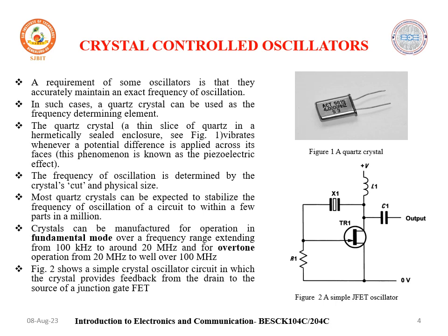A crystal oscillator generates electrical oscillations of constant frequency based on the piezoelectric property of the crystal. A requirement of some oscillators is that they accurately maintain an exact frequency of oscillation. In such cases, a quartz crystal can be used as a frequency determining element. The quartz crystal, a thin slice of quartz in a hermetically sealed enclosure, you can observe in the figure,